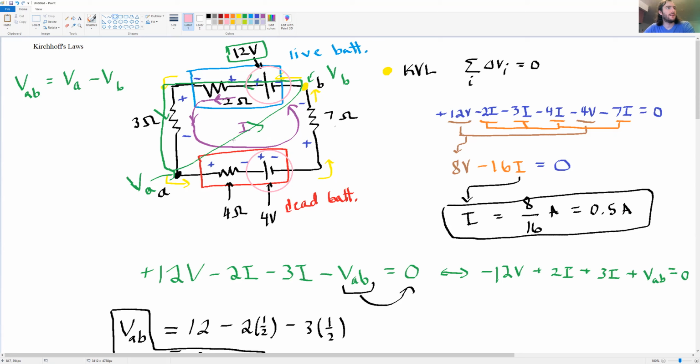Notice that in the top part of the circuit, the current is flowing from low potential to high potential across the EMF source. So the current in the top part of the circuit is flowing from right to left. That means that the EMF source at the top is supplying power to the circuit.